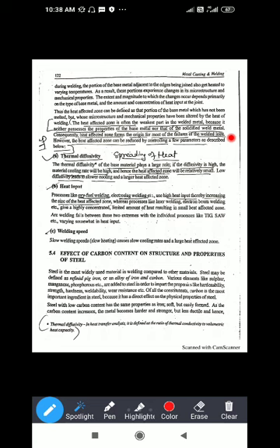For this reason, whatever heat you release, whether it is gas welding, electroslag welding, or arc welding, you should try to reduce the heat input. If the heat is high, the size of the heat affected zone will be more.